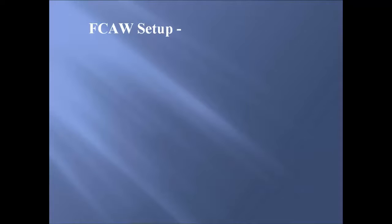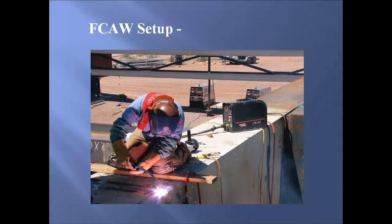Okay, let's take a look at the setup you might find in the field with the flux core arc welding process. Starting with the power source, if you look in the background of the picture, you will see the silver portable welding machines down on the ground. Following what you have covered earlier, these are producing direct current, constant voltage. In those welding machines are the CV adapters required for constant voltage. The manufacturer has placed them in the machine during the assembly process in the factory.